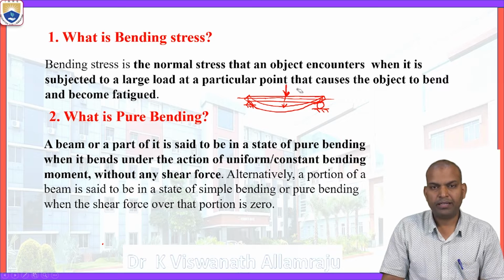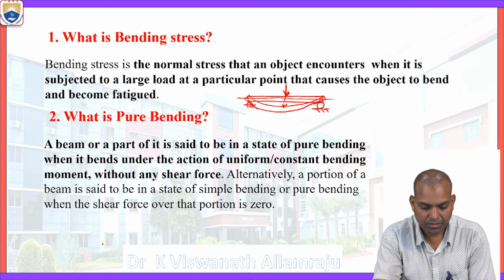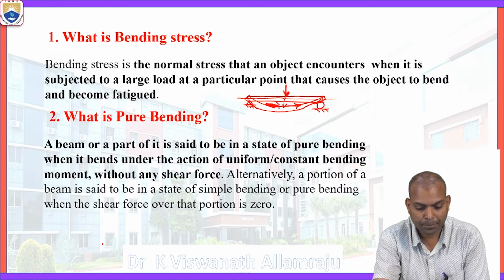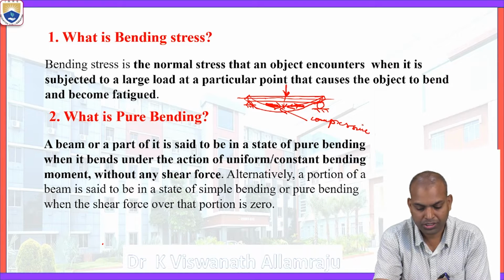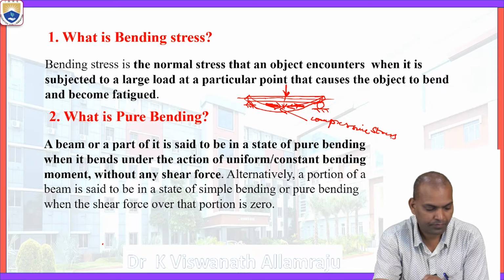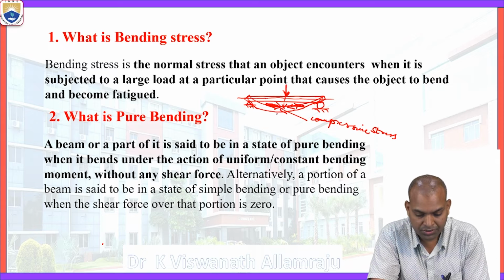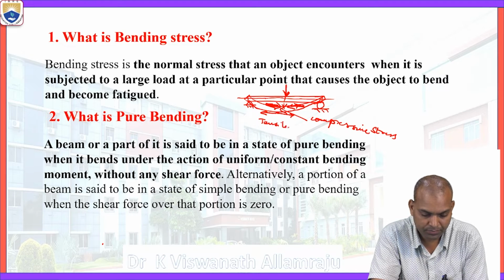Here, when the beam bends like that, the top layer experiences compressive stress, not tensile, compressive stress. And the bottom layers experience tensile stress.